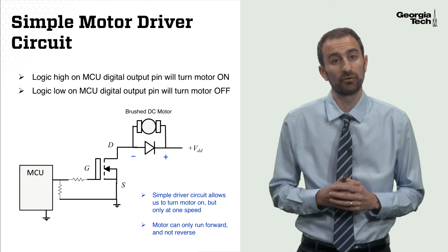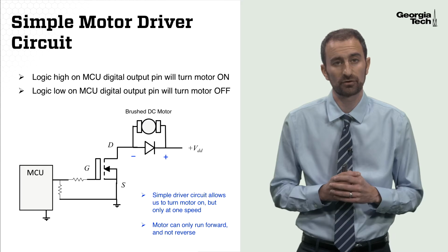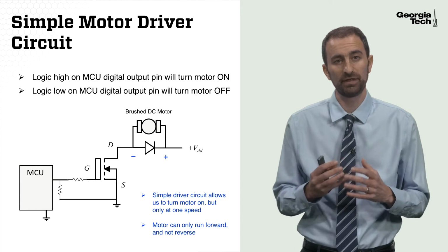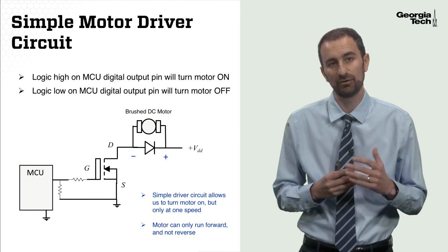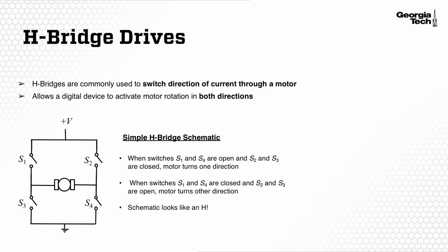Likewise, it'll only turn in one direction. With this type of circuit, we can't reverse the voltage across the motor and allow it to turn in the opposite direction. So this simple driver circuit is really only good for turning on a motor in one direction at one speed. That brings us to the concept of an H-bridge drive.